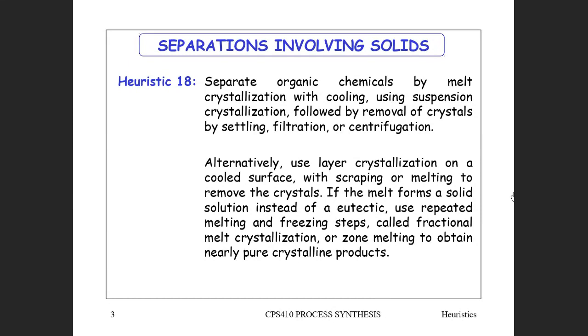The things will mix, but a great deal has happened to the entropy. So you've created a lot of entropy by mixing those two gases, and in order to separate them again, you have to provide that much energy, as in normal energy, steam or whatever, because that entropy formation is wasted energy. It hasn't occurred reversibly.